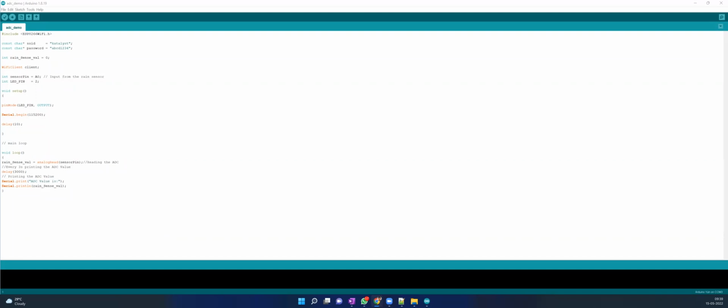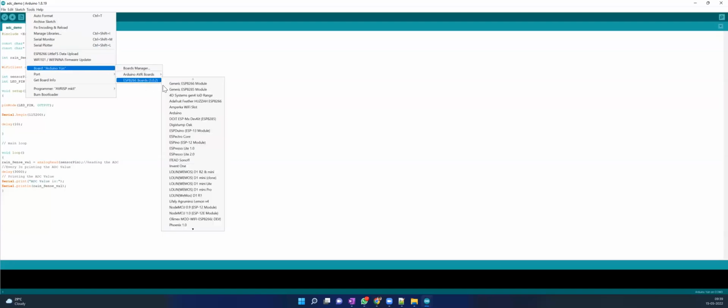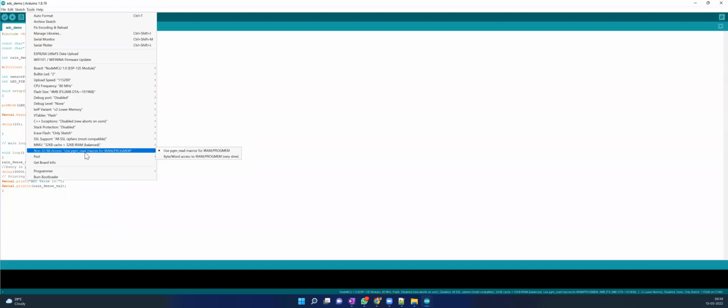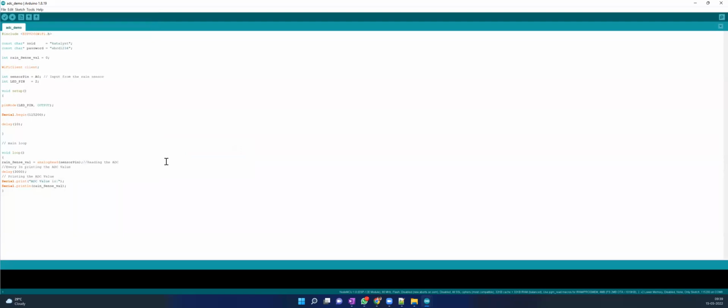Which board do I need to select? Do you remember what we have discussed? Where you were, like when we were discussing. It is actually NodeMCU 1.0. So port, make it COM8, not COM8 actually. Let me connect it.